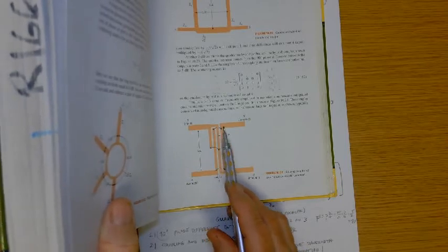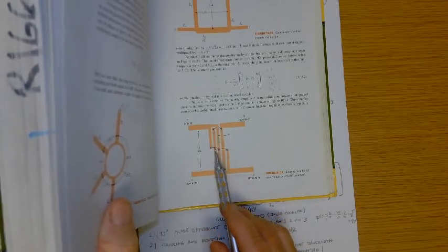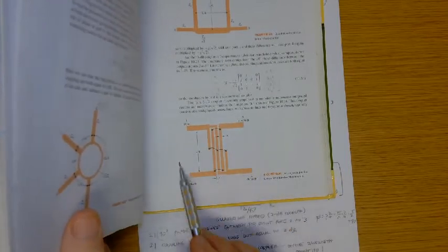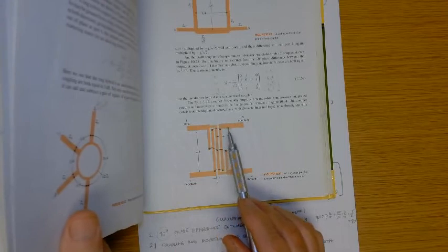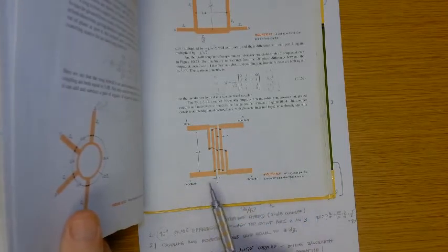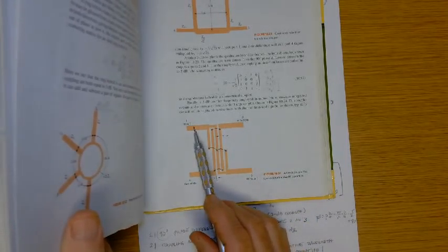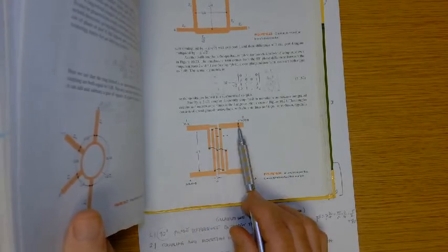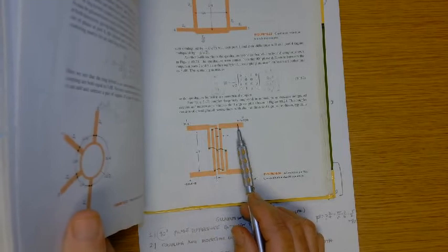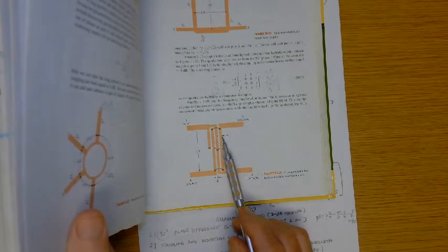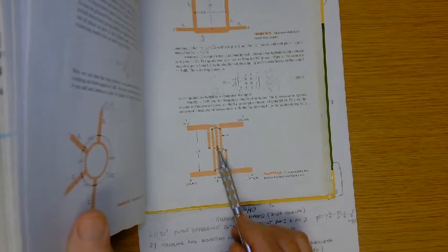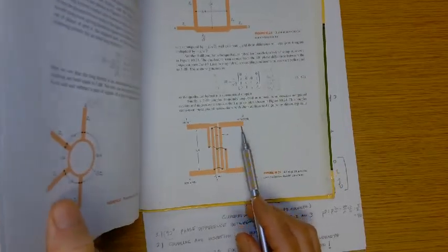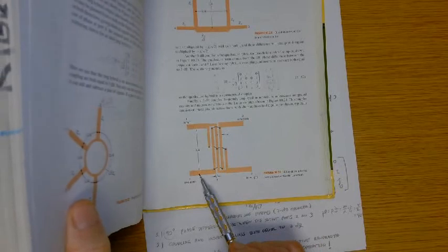These are literally wires from this line to that line. And so the nice thing about this coupler, right? So input here, that's your through port. This is your coupled port. And the amount of coupling would depend on the width of these lines and the separation between these lines, right? You could design that to have a certain amount of coupling. And then this is the isolated port, right?